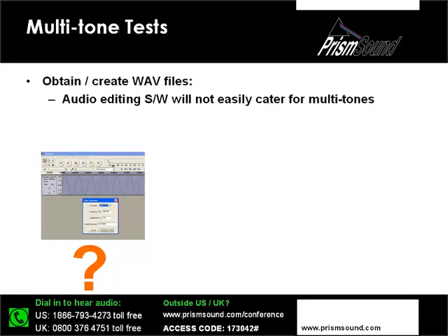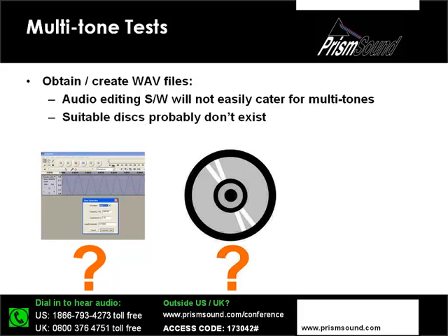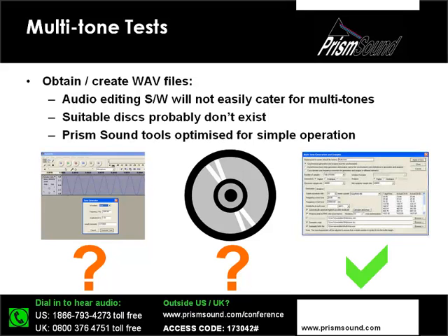When you're setting up a multitone, you need to be very careful about ensuring very, very specific signal frequencies. So your audio editing software probably isn't the best solution for creating a multitone. Again, test discs probably don't have exactly the multitone that you need for your application. They may do, but they may not be the best way of creating your test files in this case.